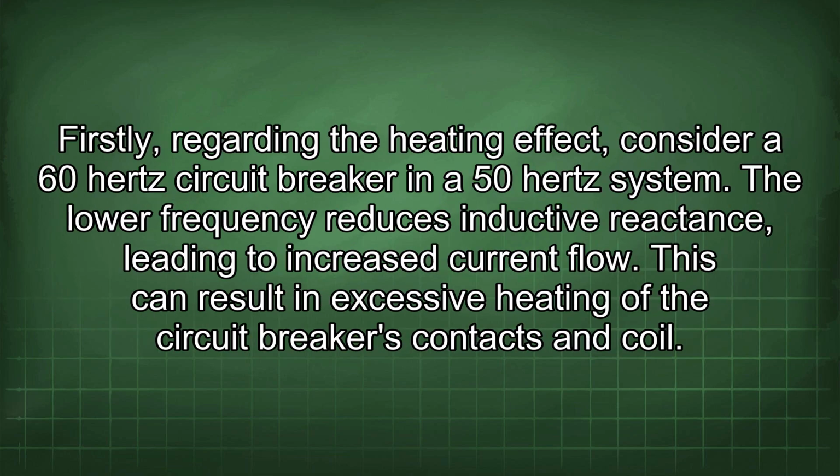Firstly, regarding the heating effect, consider a 60 Hz circuit breaker in a 50 Hz system. The lower frequency reduces inductive reactance, leading to increased current flow. This can result in excessive heating of the circuit breaker's contacts and coil.